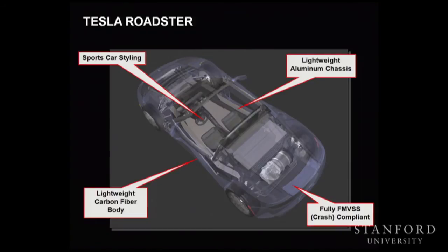Oh, so this does address some important things though. Battery packs are expensive, so you're really incentivized to keep that vehicle lightweight and aerodynamic. Two ways that you do that right off the bat are an aluminum chassis and a carbon fiber body. The Model S is all aluminum. It's an aluminum body with some aluminum substructure undercarriage. That's one of the ways in which electrics tend to be different. There's a lot of impetus to make internal combustion engine vehicles lightweight as well, but the lever just isn't as strong, right? It's not pushing as hard to bring those things down.